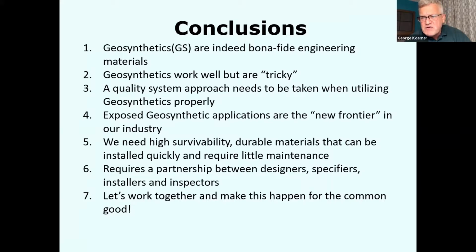It has great UV. To stabilize it even further, I've seen it hit with a polyurea, a bitumen, and the bitumen I don't recommend because of the hydrocarbon in it, or a latex. But both the latex and polyurea have to be sprayed, applied in the dry. They don't like the wet very much. So that has to be done as a preamble.